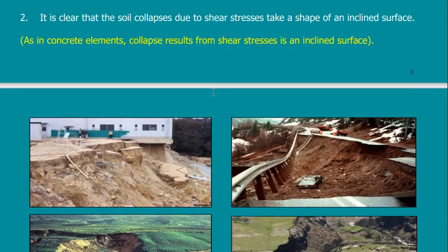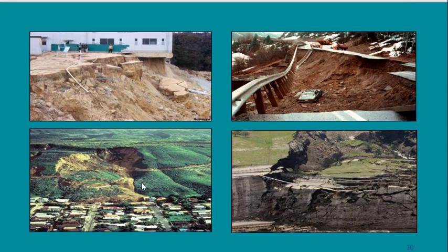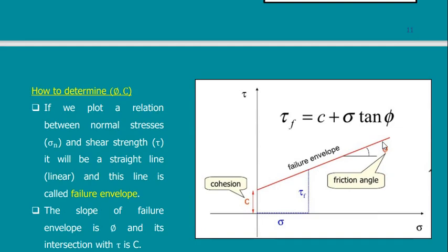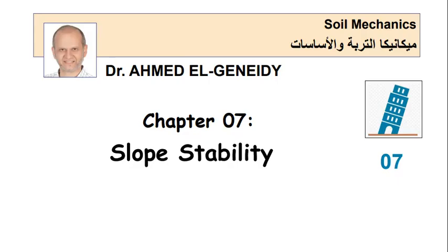We used this equation. What is important in the shear strength? To prevent all of these failures. All of these failures are shear strength failures, because this was the figure that we were discussing before the lecture, where we need to measure an angle. Here we need to measure an angle. So once I draw this equation, we can measure this angle to be the phi of the soil, and measure this intercept with the y-axis to get this C value. So I can measure the C and the phi of the soil using this test, which is the test here, not this one.